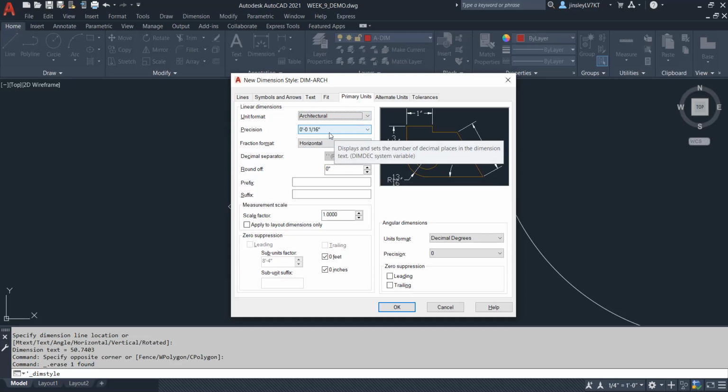I would never expect a contractor to measure to 3/64 or 7/64. That would be a little bit ridiculous. Even getting into 32nds or 16ths, they won't always be super happy with you. So the most I would ever go is 16ths. Most tape measures and measuring devices on site won't go beyond that, okay, and are common and accessible to people.